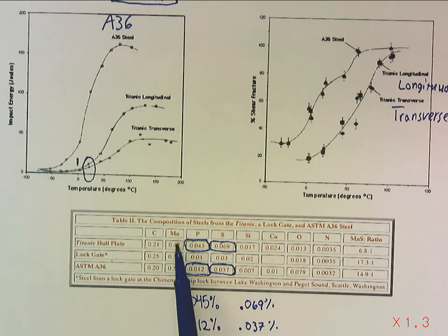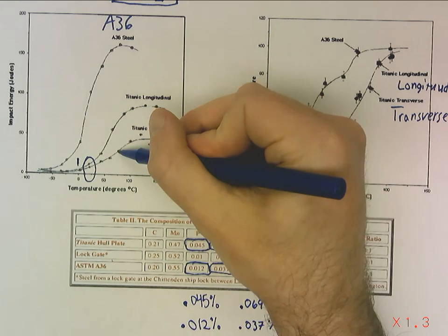So manganese is generally a good thing, especially if your sulfur is high. Here we have high sulfur, slightly lower manganese, very high phosphorus. This is a very high phosphorus amount. Phosphorus is pretty much universally bad for iron-based alloys. Even in such tiny amounts, they contribute in particular to low toughness and a high ductile to brittle transition.